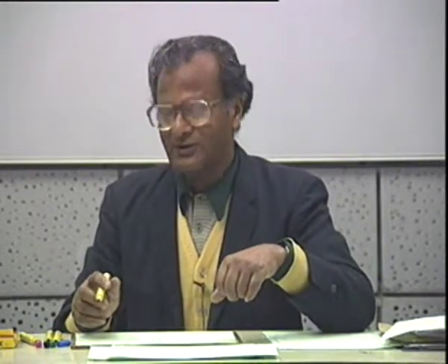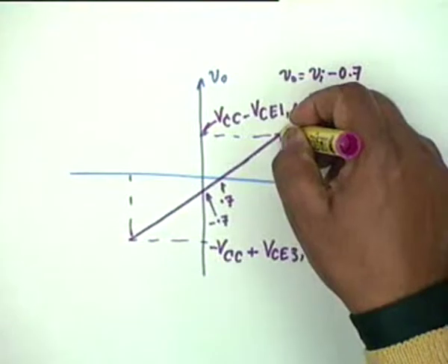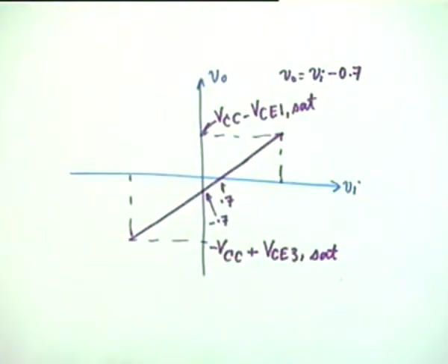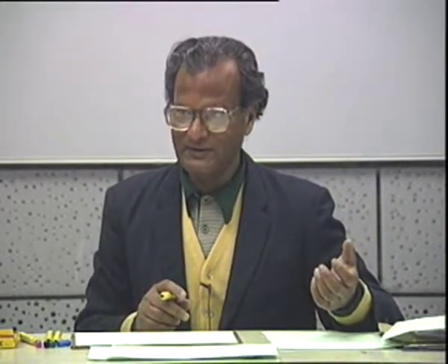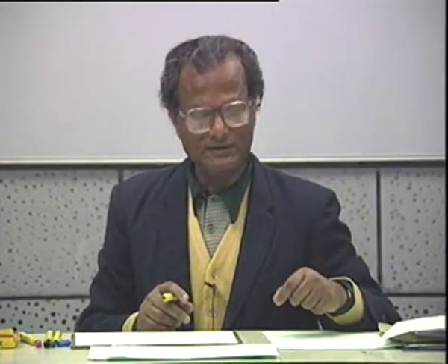You must be well within these limits. This figure only shows the limits. You should not operate the transistor so that the peak swing goes here, because then you are asking for distortion. You could as well go to a class AB or class B amplifier. Class A amplifier is for low power level and very little distortion.